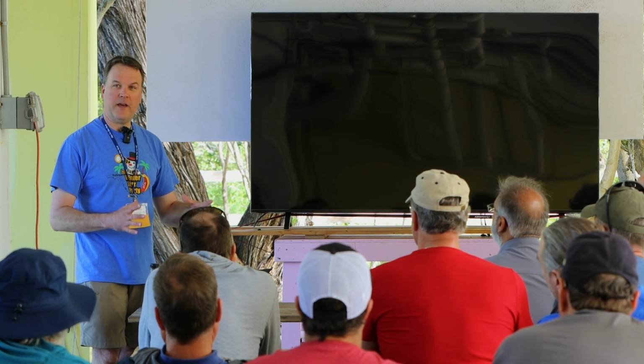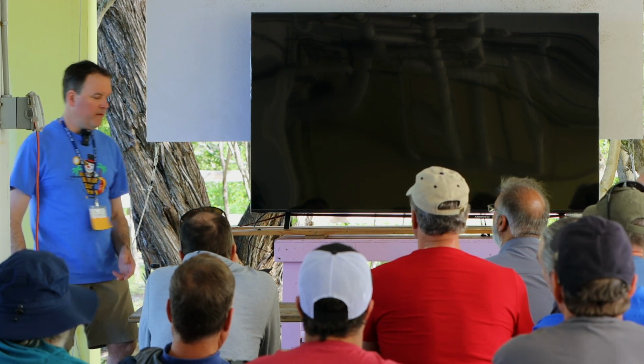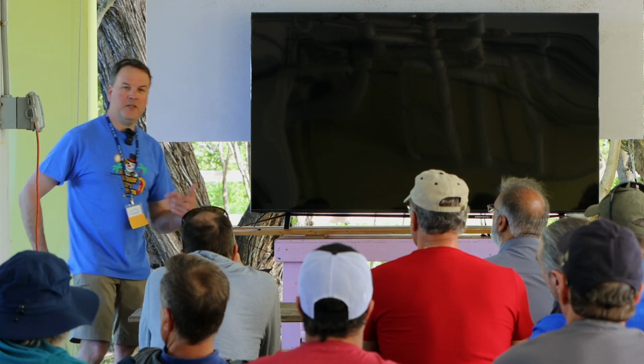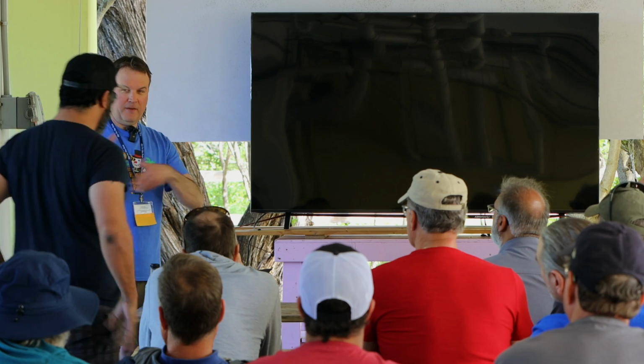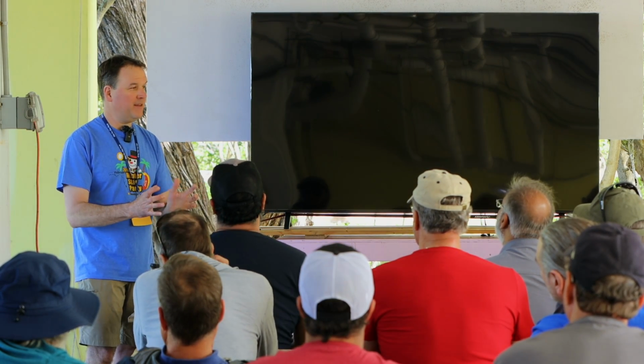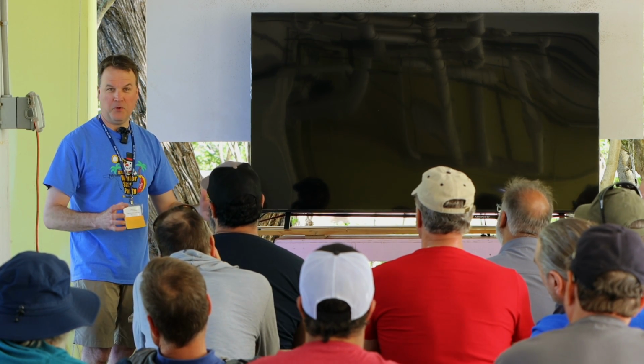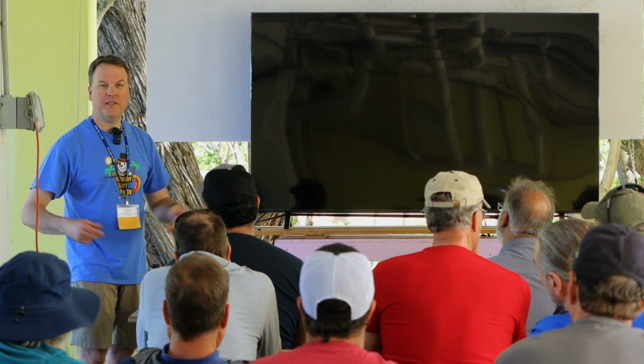And it will get tighter and tighter and tighter, and in wintertime this can be a big deal. However, the metal is also going to shrink faster because it gives up its heat more quickly. So it's going to shrink more quickly than the glass at first, so it might pinch it, and then the mirror might catch up depending on how much room there is around the mirror. So weird things can happen.